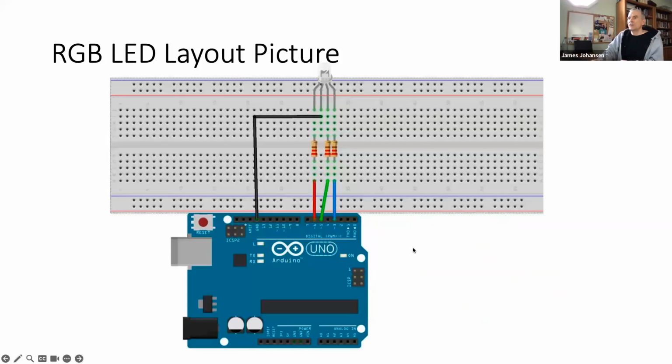So what we're actually doing, and so I know, David, I saw the size of yours, it was actually smaller, but you're going to have with your wiring board, this is how you start to hook things together. And you actually have exactly where you're going to be putting those items together. And so this is this LED that actually has 3 LEDs built into it. And so you have this G and D that stands for ground. And so you need to tie this pin here to ground.